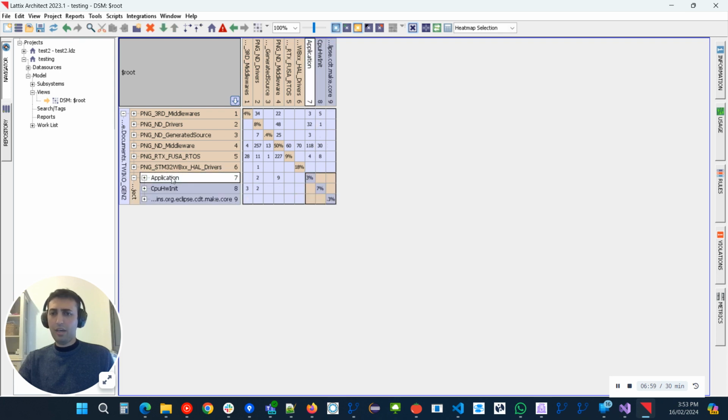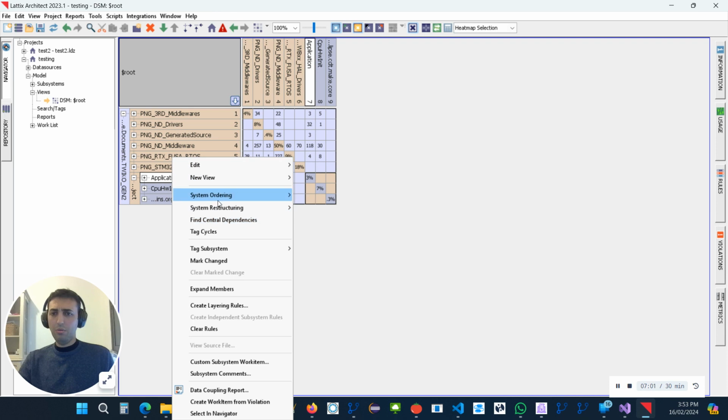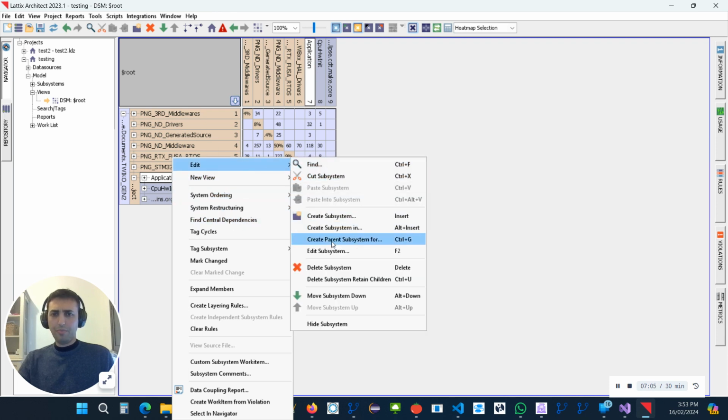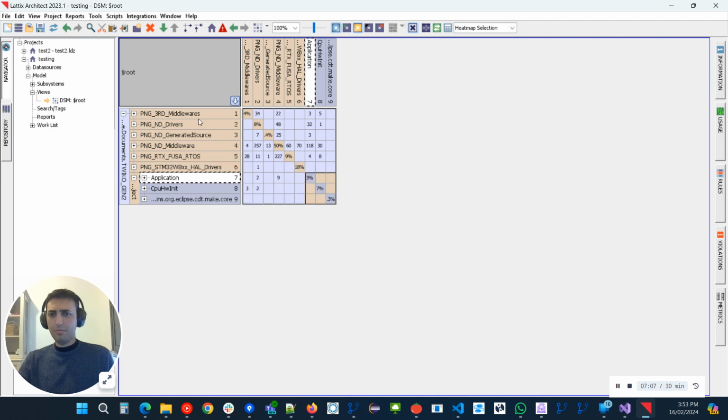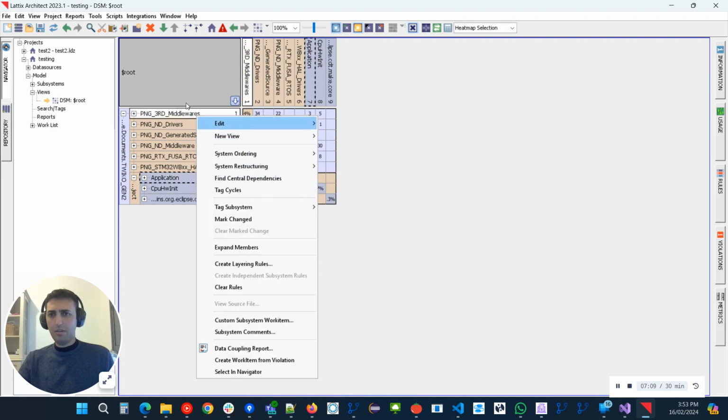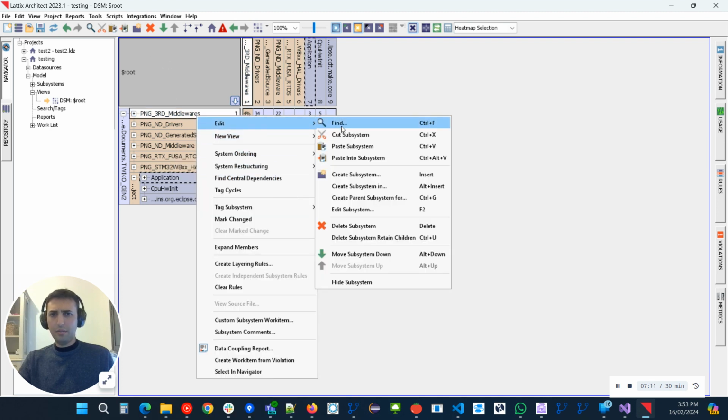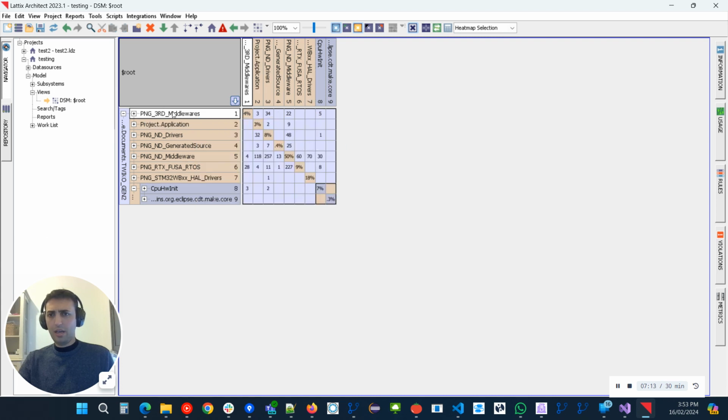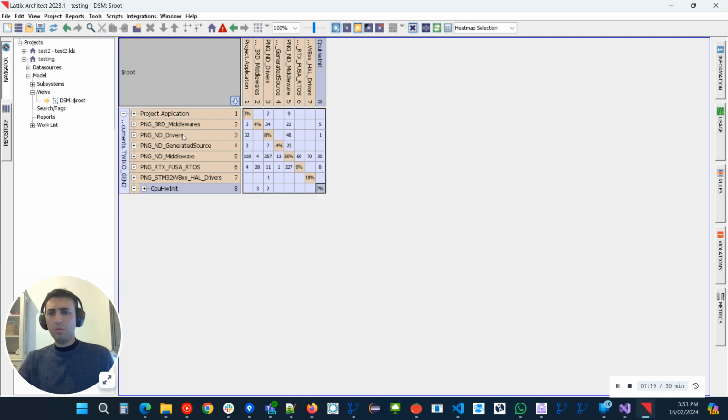So how do you take them out? You click here, you do edit, cut subsystem. You can just paste it up here, edit, paste, and now it's up here. Just move it up, etc. And I can delete this one. I won't do all the cleaning here because I already did that.